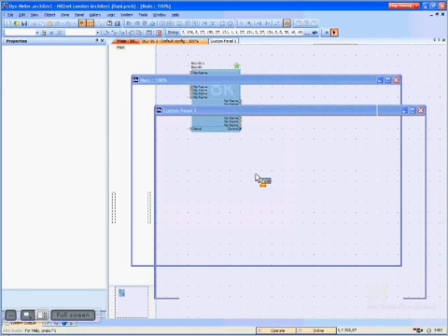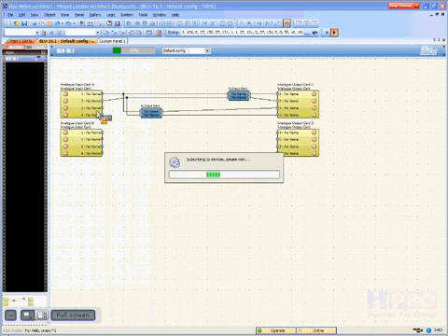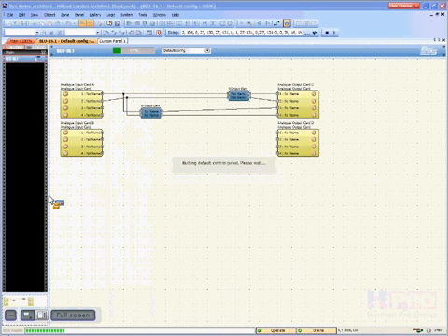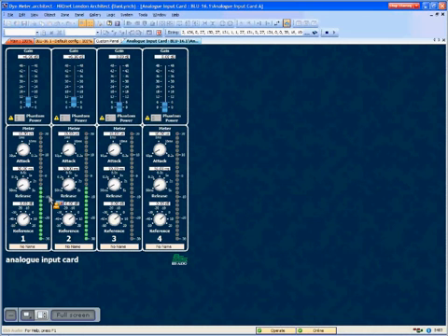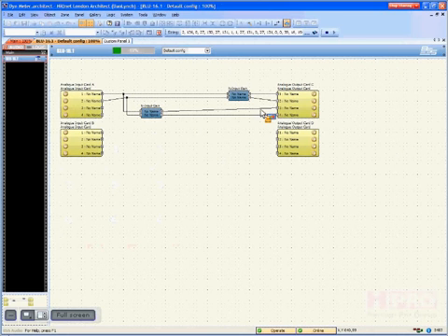Let's go online to this turkey, now that we've finally updated our firmware. Dynamic meters. In the past, we always had meters over here, which you guys will see in just a second. And we've got our output meters. And if you wanted to check anything in between, like right now, let's say on this design file, I have output at 3 and 4, but no output on 1 and 2. I'm trying to figure out why I can't hear anything. Well, if I hover over a wire, a meter pops up. Hover over this wire, a meter pops up. This one says negative 10 dB. This one says negative infinity, so maybe this input gain has got the problem.